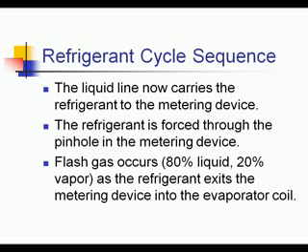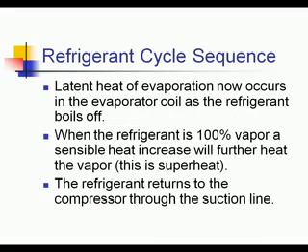That's what cools it. Once the refrigerant is 100% liquid, a sensible heat change occurs as the liquid subcools. Subcooling is that sensible heat change. It's measurable because it's sensible. The liquid now carries the refrigerant to the metering device.